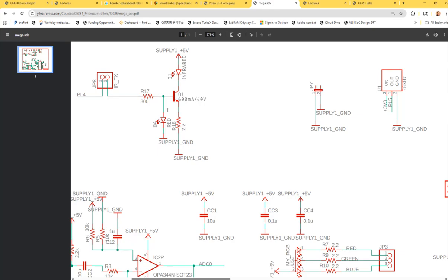No, before you change the component. I know the electrical signal got delivered to this guy, right? And I know my board works. There's a good board over there. And I'm using this emitter to send signal to the other board's receiver, okay? But it's not receiving anything. The electrical signal arrives at the LED, but it's not receiving anything. What's the next logical step?